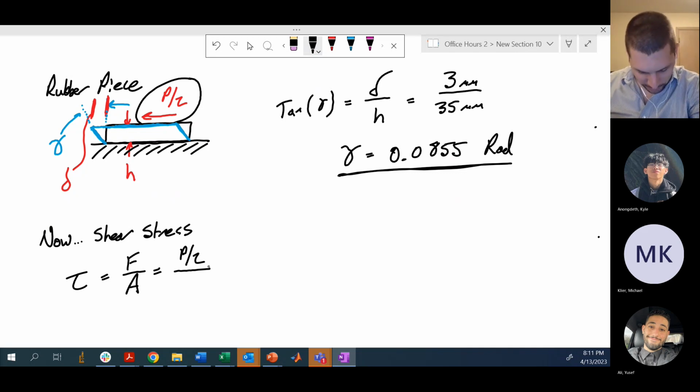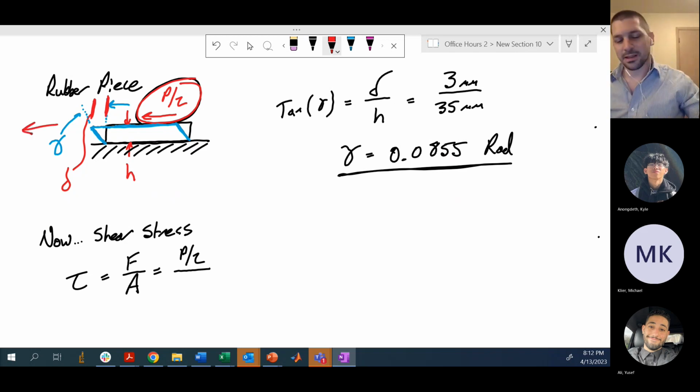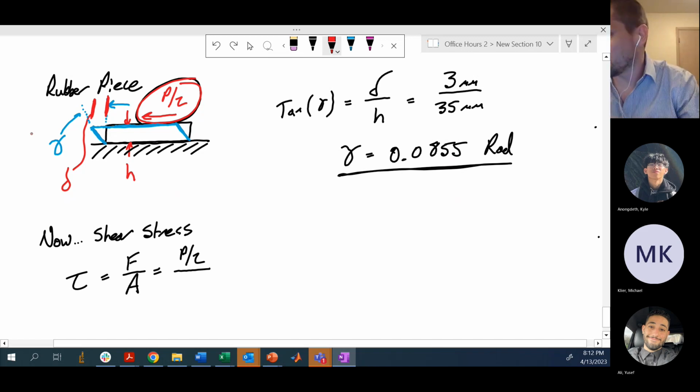And for this, you really want to get back to the fundamentals of mechanics about the shear stress. What direction is the stress and what face is it acting upon? Well, in this case, the shear stress has some directionality associated with it, which is like the left direction, okay? And then what face is that shear stress acting upon? Well, that shear stress is acting upon the top face of this rubber bit that's in contact with the plate.